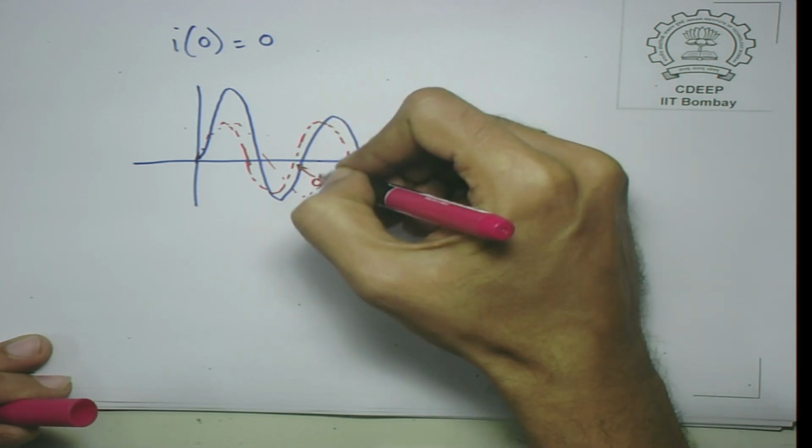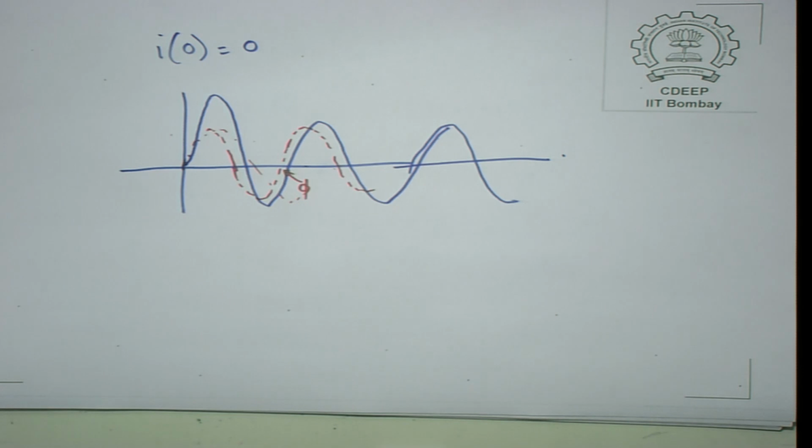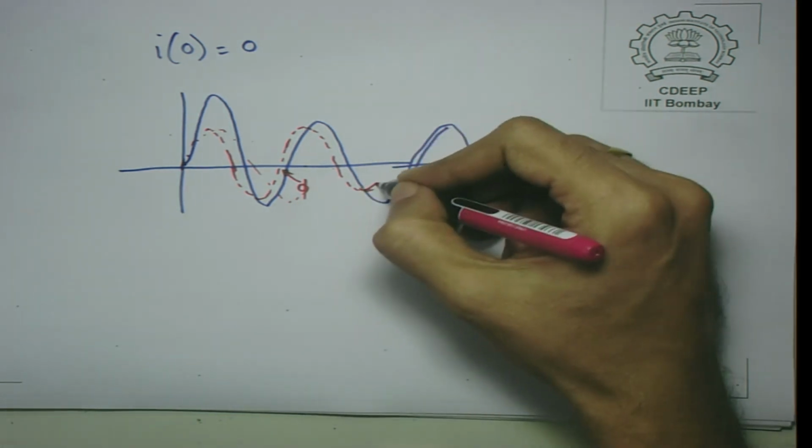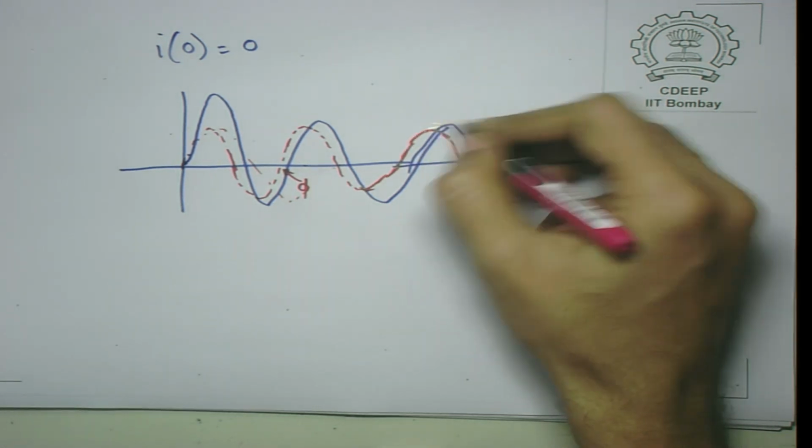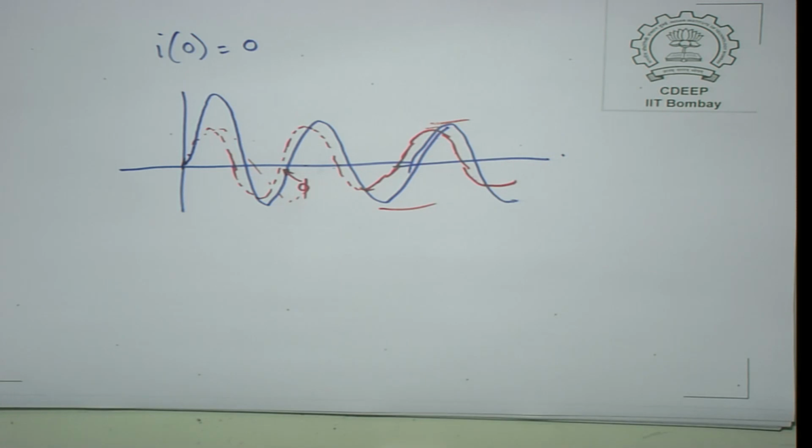I have not drawn it very well, this would be 45 degrees as per our example. So, in steady state of course the voltage and current relationship is simply given by the current being scaled by the voltage, scaled by the term root of R square plus omega square L square. So, this is how you expect the sinusoidal steady state response of an RL circuit to be.